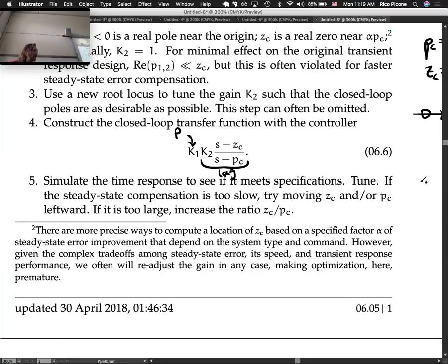So that's the process in terms of an analog controller, but we don't typically do an analog controller anymore. Typically instead, we're going to take that encoder measurement and turn it into a digital signal. We're going to say, okay, pin 7 is maybe my encoder, and it gives me the current position of the motor. I take that, and the user says, I want 30 degrees. It's giving me 20. I compute then what the controller gain times the error is.